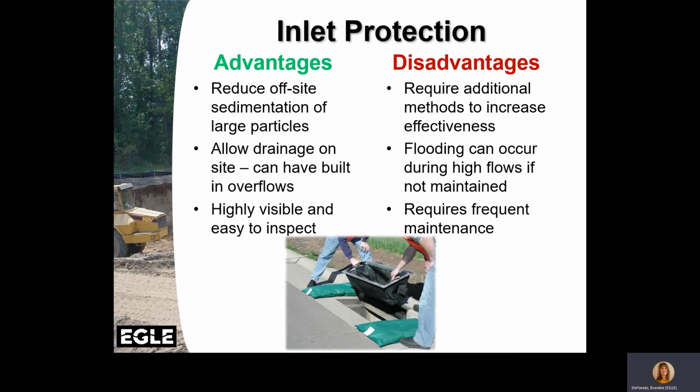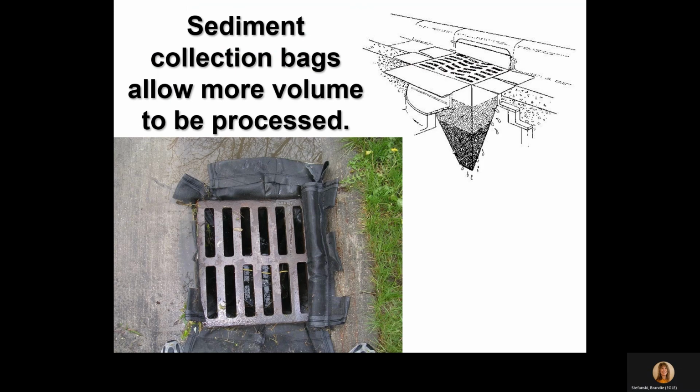There is no one size fits all when it comes to inlet protection. The effectiveness varies depending on soil types and is not highly effective with fine silts and clays. Pre-manufactured devices are preferable. Placing rolled fabric under grates is never recommended. A few counties require the use of silt sacks instead of fabric drops. We don't prefer fabric drops either because of the maintenance issue.